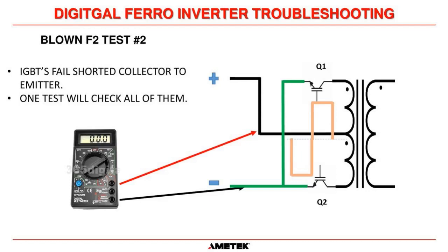First few times I worked on these machines out in the field, I had one transistor fail, and I thought, well, we only replace one with the SCR type bridges. I'm going to replace this one. And I had other people tell me otherwise, but I said, no, I think I'm just going to replace the one. I think it'll work. A day later, I was back at the plant replacing the other one. So that was a lesson learned. For this type of transistorized bridge, if one fails, we go ahead and change out both of them. Okay. Fortunately, they almost never fail, so they're really rugged and reliable.